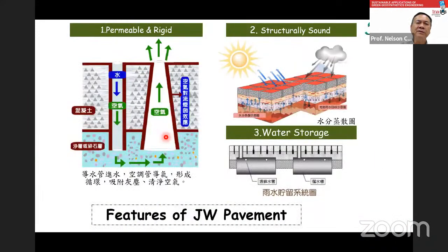Okay, this is the principle of this permeable pavement. The water gets through this hole, and the other hole has a smaller diameter at the top and a larger diameter at the bottom. So the air will go like this, circular air. Circular air will keep the temperature of the air about constant. So during summer, it is not very hot. During winter, snow will not accumulate. Okay, this air, but also water, can accumulate here. So actually we can put a LID, sponge city or water tank at the bottom of this portion and make more storage if needed.